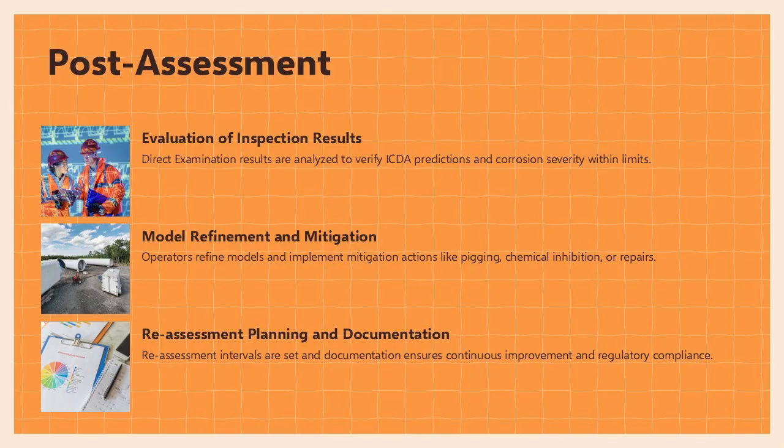Post-assessment is the final step of the ICDA process and focuses on evaluation, learning, and decision-making. Results from direct examination are analyzed to determine whether the ICDA predictions were accurate and whether corrosion rates and severities are within acceptable limits. During this step, operators assess the effectiveness of the models and assumptions used during indirect inspection. If necessary, models are refined to better reflect actual pipeline behavior. Mitigation actions are then identified and implemented.